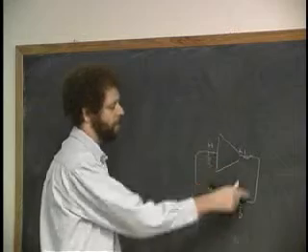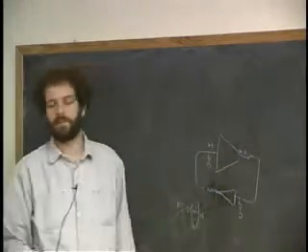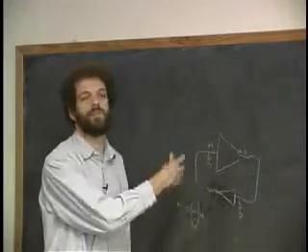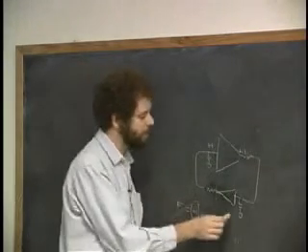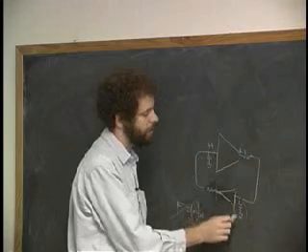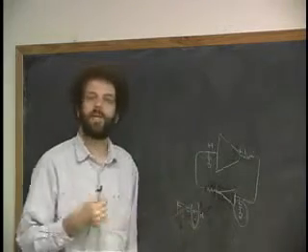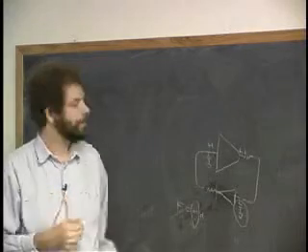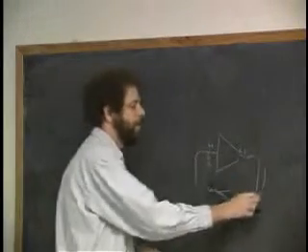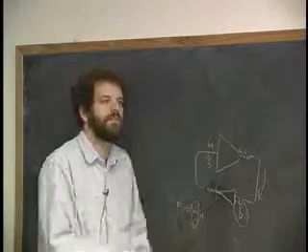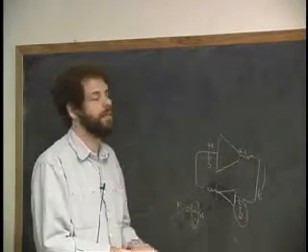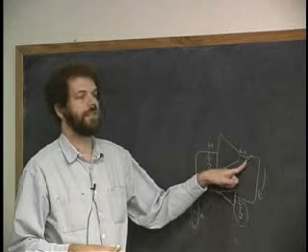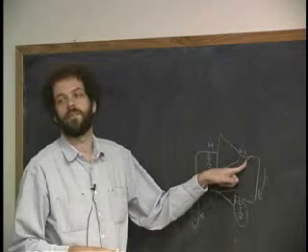And this RC delay, as it's called, resistive capacitive delay, limits the speed of the propagation going around the loop. In particular, the point I want to get across is that this capacitor is kind of the equivalent of the mass, how heavy the circuit is, how much current it takes coming out of this wire here to get this thing to move its voltage up or down. Thinking hydraulically, this is the bathtub, and this is how thin the pipe is going to fill up the bathtub.